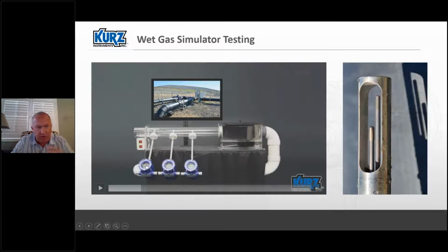One has a 10-degree overheat, only 10 degrees Celsius overheat. So this thing's only running about 20 degrees Fahrenheit above the process temperature. This flow meter is going to be at the 55 degrees C overheat, which was our standard before, and we've now increased our standard to about 75 degrees C overheat. And then this one will be the 300 degrees C overheat sensor.